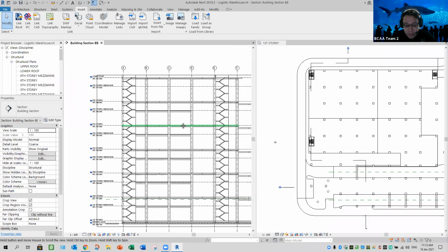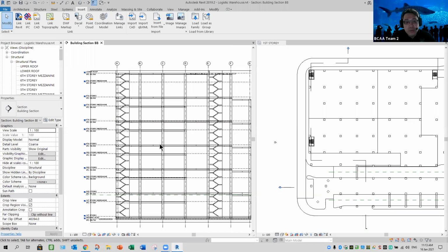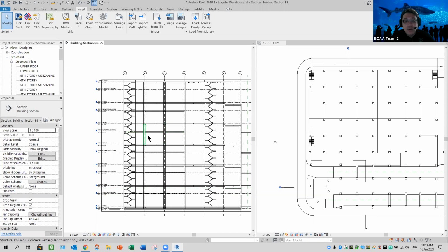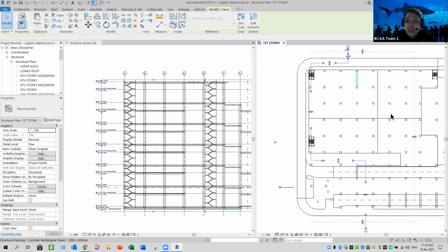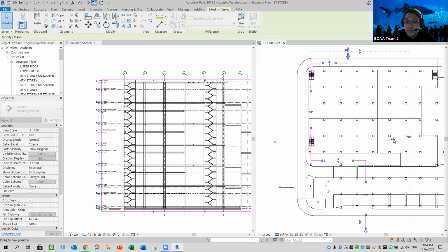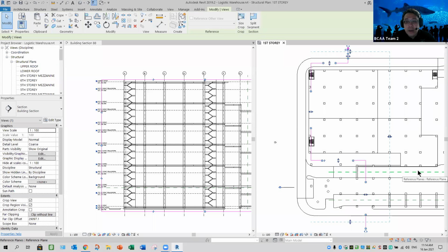Then of course, sometimes you want to restrict people to see the depth, how far, or certain clearance. You need to adjust this width, the depth, the far clipping depth. Then you will see that your view will start to change. So which one you want to show people, which one you don't show people. You can drag.